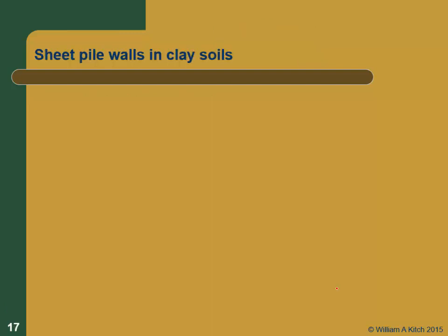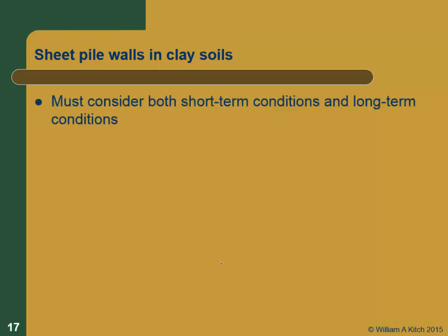Okay, well, let's talk about what happens with clay soils. So early in the quarter, we said, don't design walls with clay behind them. Well, if you're going to install a wall in some marine environment that's got clay, there's nothing you can do about it. So you've got to know how to deal with clay soils here. So it's important that you consider both the short-term and long-term conditions in this case.